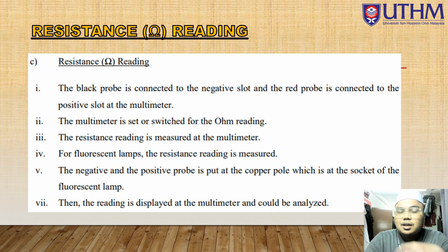For the resistor reading, the same thing is done, which is we just change the black and red probes to different positions on the circuit, and we just turn the dial in the middle to read the ohms. Okay, that is how to read the resistance.